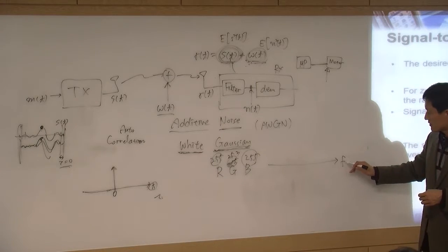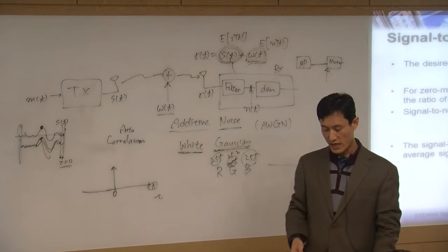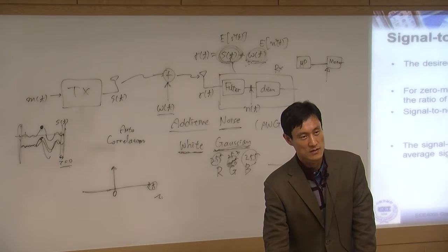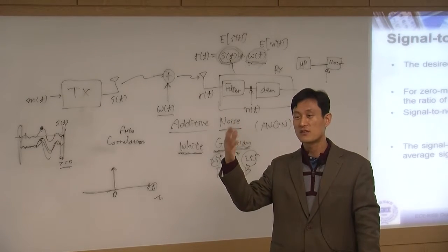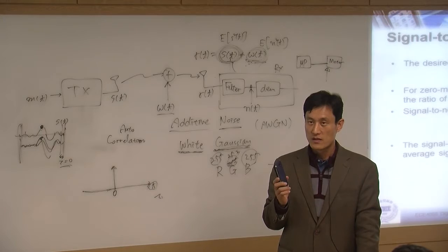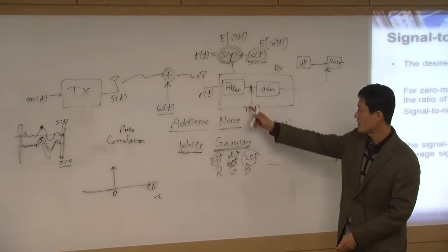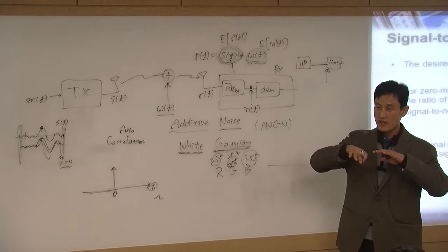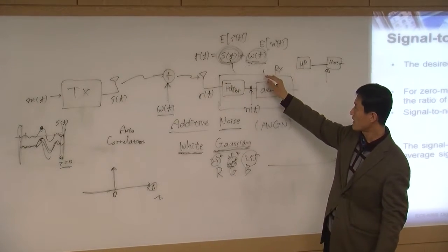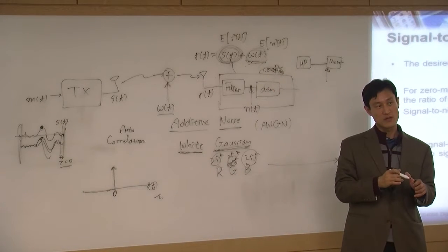In the frequency domain, we have a carrier frequency. Your cell phone is using 1.8 gigahertz, right? But in the air, there are so many different frequencies. But our cell phone is using only 1.8. So the first thing in the cell phone is a filter, and this filter filters out all the other frequencies. It only passes 1.8 gigahertz, because that's what we need.